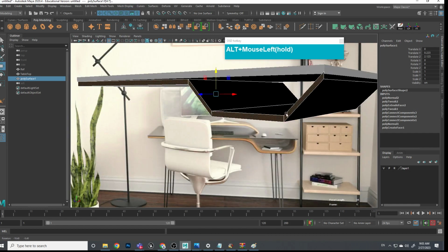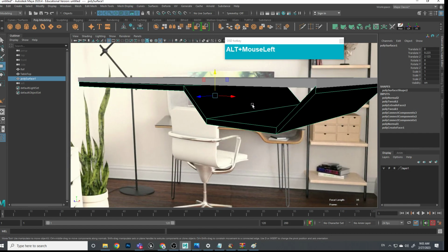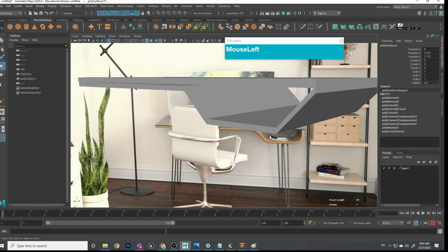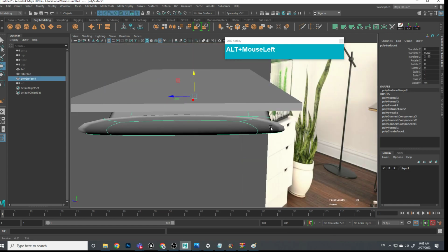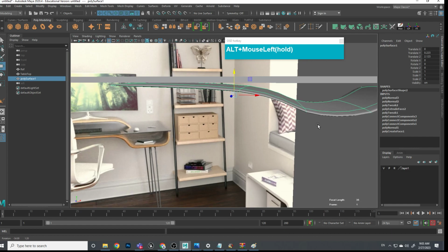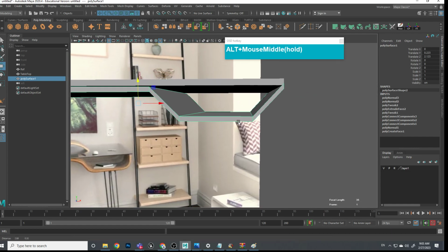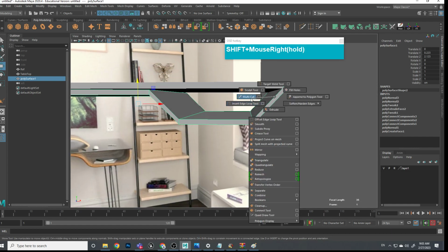Okay, right now all the faces are black. Alright, then I will do another operation, mesh display reverse. Okay, now this should fix the subdivision problem. So press number 3, yep. Okay, so this is what I expect to see. Next, I just had to insert supporting edge loops.